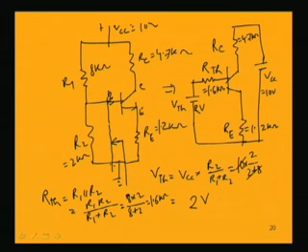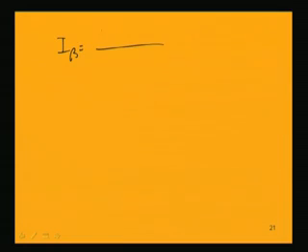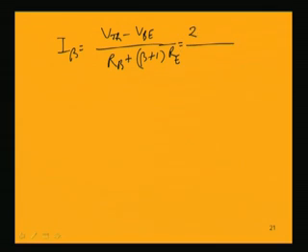So, now this is the base current IB, this is the collector current IC, this is the emitter current. So, I will be finding out IB. IB is equal to V Thevenin minus VBE by RB plus beta plus 1 RE. Putting down these values here, V Thevenin we have found out to be 2 volt, VBE is standard 0.7 volt for silicon. I should use not RB here, R Thevenin should be proper. So, R Thevenin we have found out to be equal to 1.6 K.